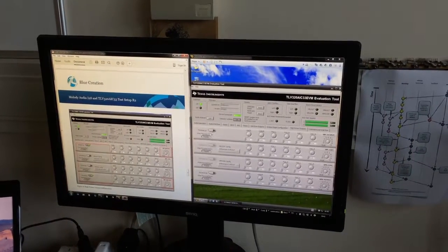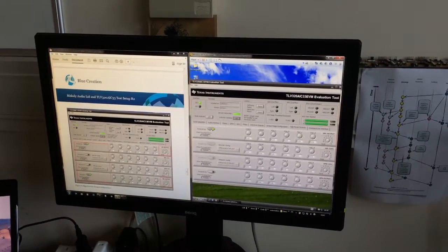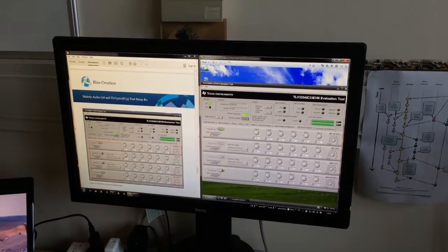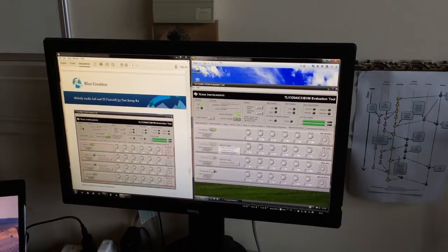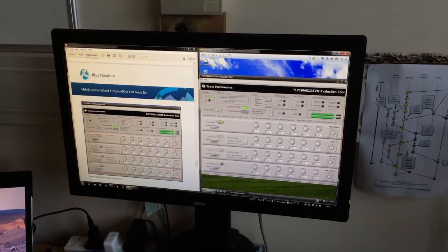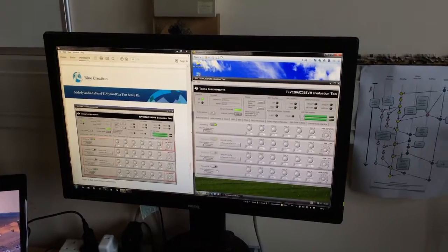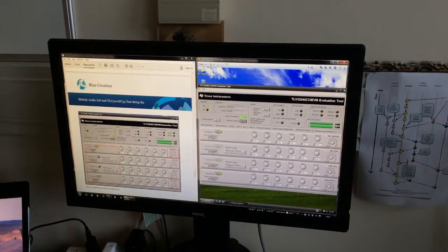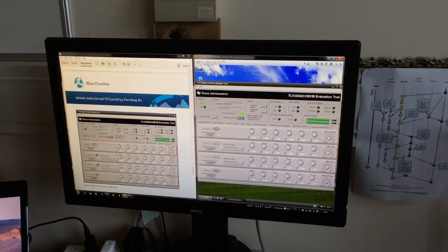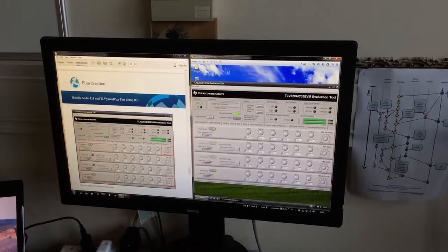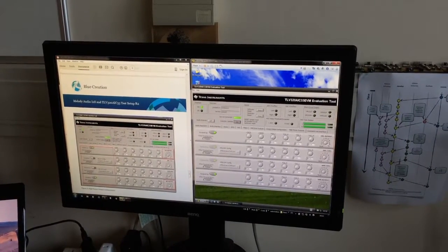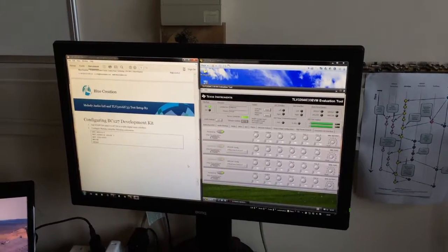What we need to do is enable the first interface, the HPL output. For the HPL COM, set it to differential to HPL out and then disable it. Also enable the HPR output, and for the HPR COM, set the differential to HPR out and disable it. Now you need to set some volume on your outputs. They don't need to be the same, but it's nice to be able to hear what music is playing.